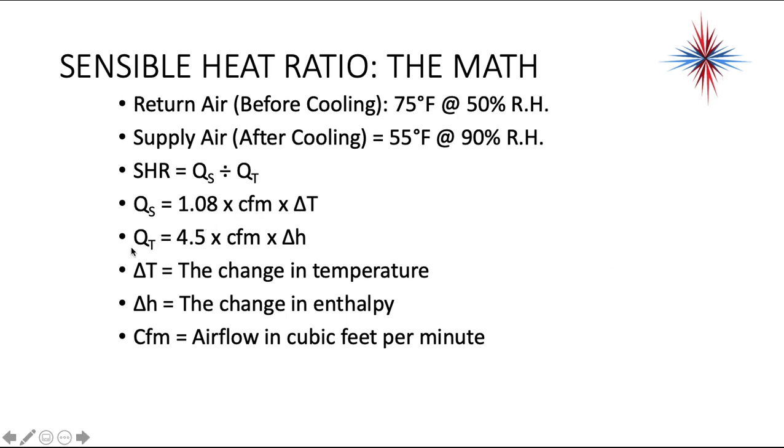QT, which includes latent heat, the formula is 4.5 times CFM times the change in enthalpy. So again, delta T, delta H, CFM.